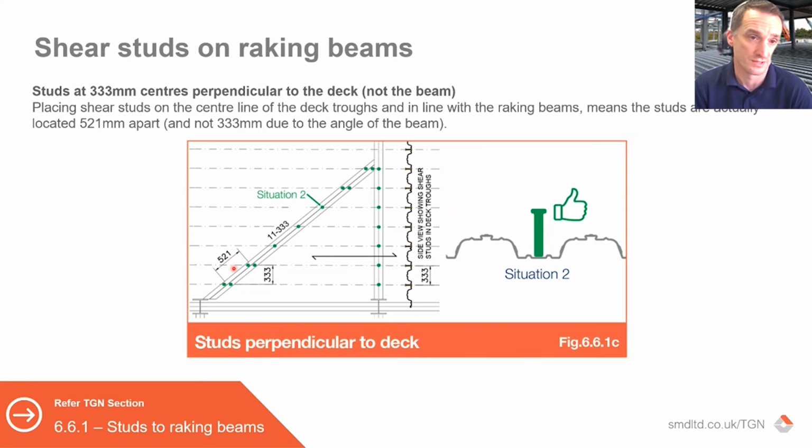If the beams aren't designed composite, then shear studs are obviously not so critical. You may be using them for robustness or other purposes, but the spacings won't be as critical as they are when the beams are composite.